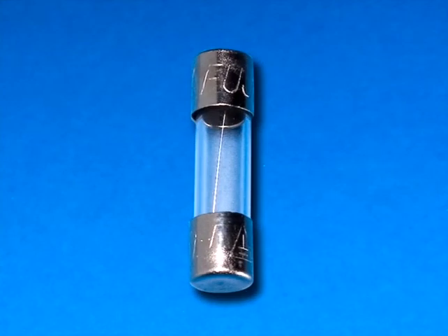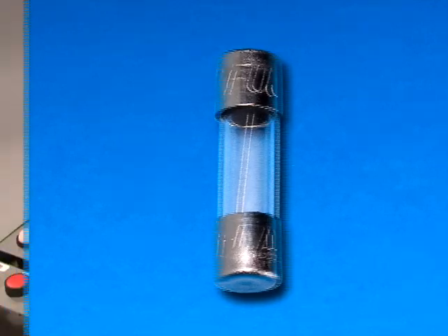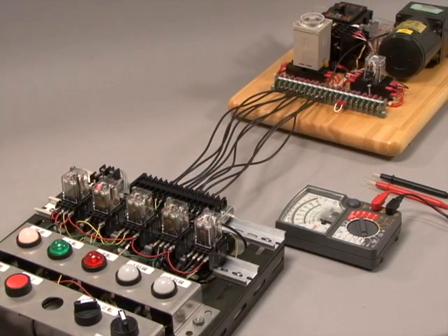You can usually determine the state of a glass tube fuse by looking at it. If visual confirmation is not possible or is inconclusive, voltage can be measured at the output side of the fuse. Even if only one fuse is blown, voltage at the output side will be zero.